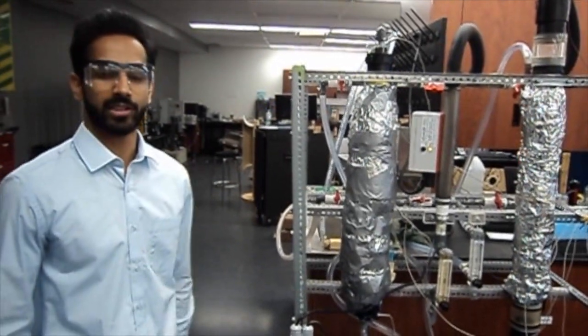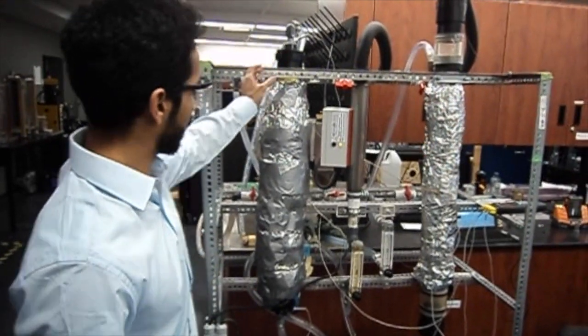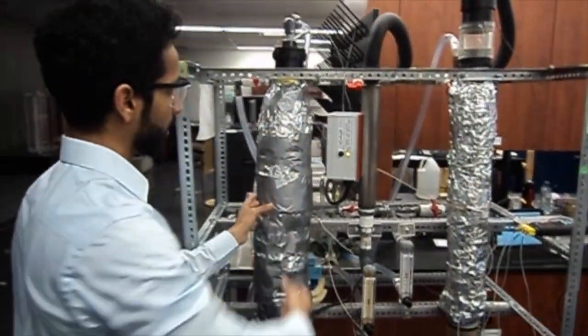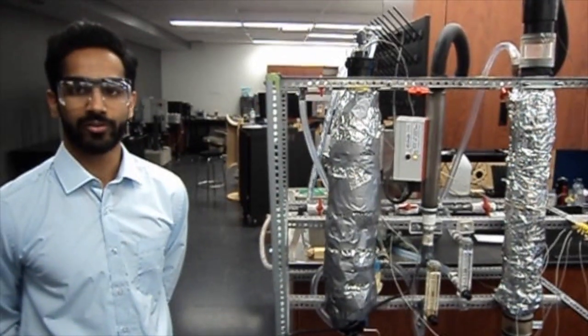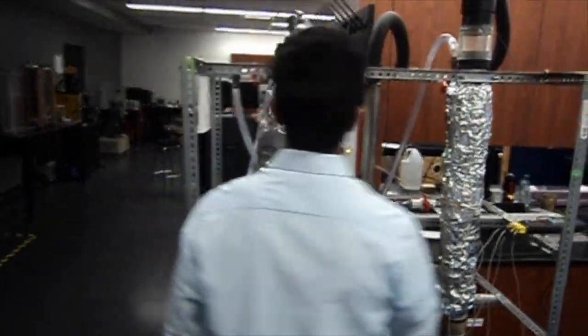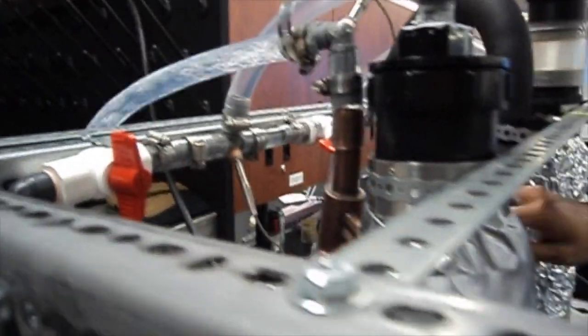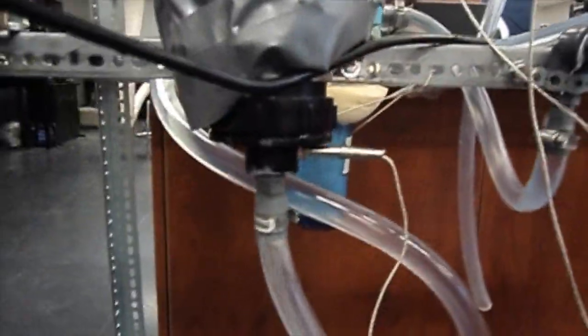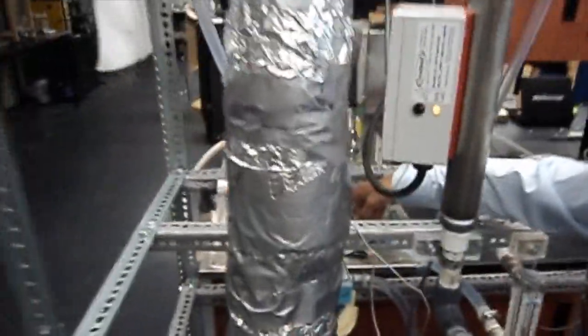There were 3 tests that were conducted with this heat exchanger. One with the swirler at the top of the heat exchanger, another with the spring in the heat exchanger, and a third test with the swirler and the heat exchanger used together. Temperature was measured at 4 different spots. Hot water inlet is over here just before the hot water inlet of the heat exchanger. The hot water outlet is at the bottom of the heat exchanger over here. The cold water inlet is over here just before the cold water inlet to the heat exchanger. And the cold water outlet is just before the drain here.